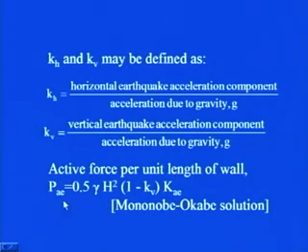It is beyond the scope of this course to know the derivation of this particular equation, but it can be done easily. But the main concern is that you must be aware of how we can analyze and design the wall for earthquake condition. This is a very well known equation and it is known as the Mononobe-Okabe solution.